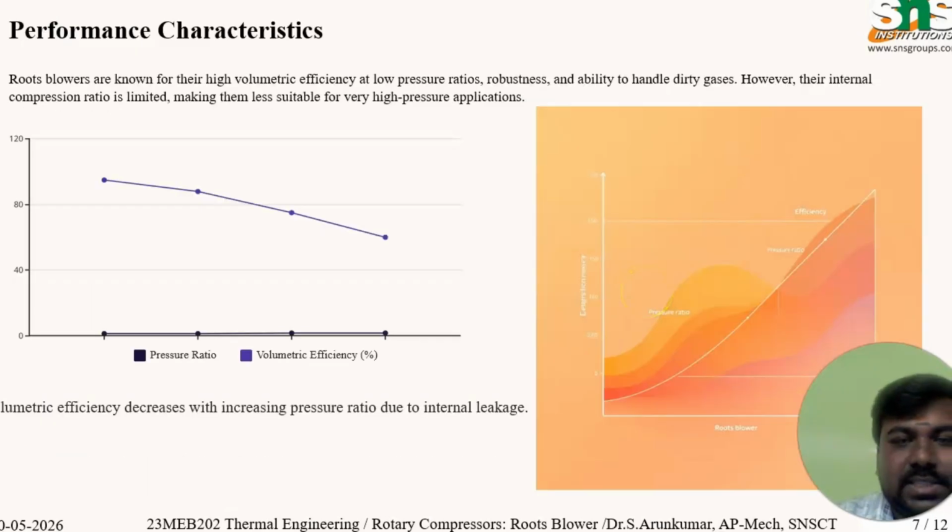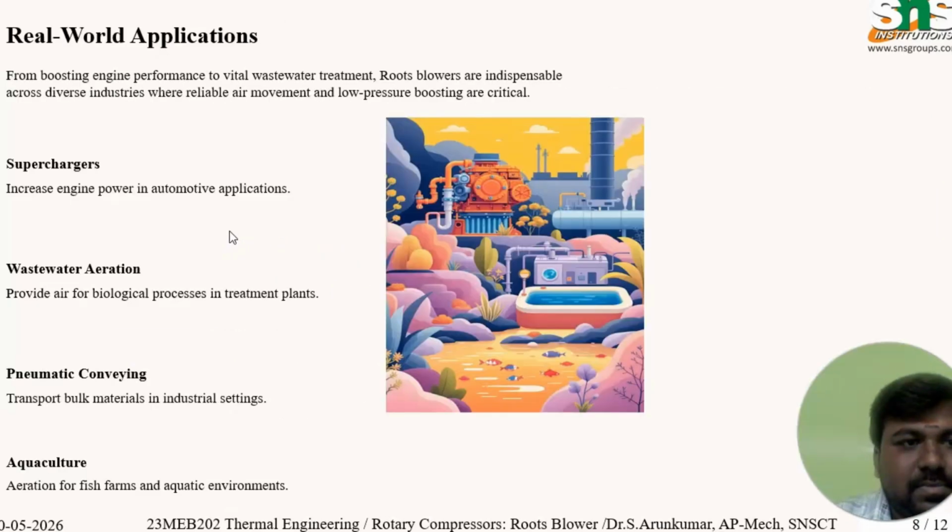These are the stages, and some of the performance characteristics are pressure ratio as well as volumetric efficiency. The volumetric efficiency decreases with increasing pressure ratio due to internal leakage.